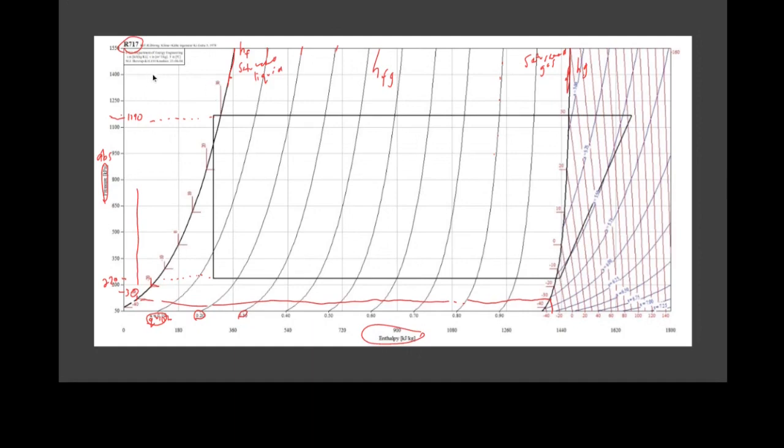Now, other things on this chart: the state of the refrigerant on this side of the line is subcooled liquid. That's going to be important for us because we're going to keep looking at subcooling and seeing how it's important and why we want, in fact, to subcool our liquid. Now, subcooling isn't a great thing when we are dealing with steam plants, right?